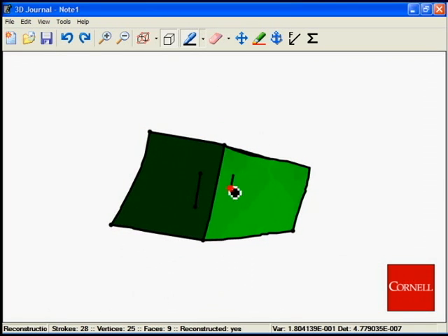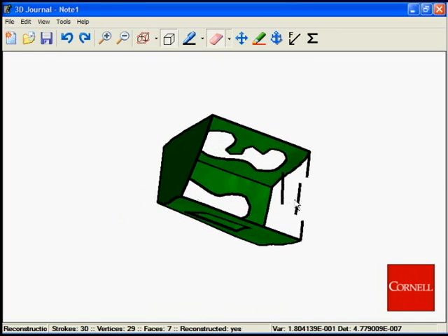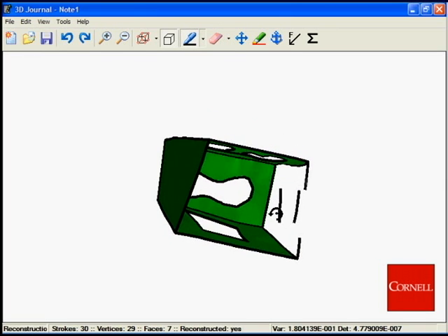Here, the user is adding a complex hole to the object by sketching lines directly onto the object's faces. The Point Erase tool is then used to erase the line between them. The resulting vertices are then rejoined to create 2 new faces that define the hole.